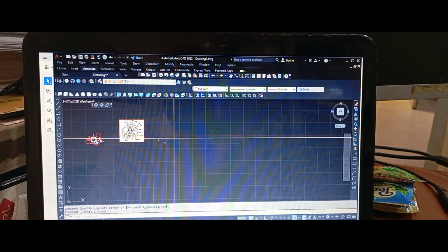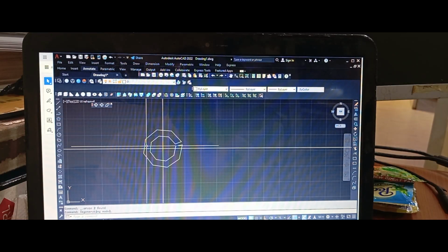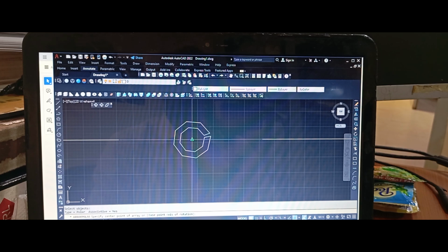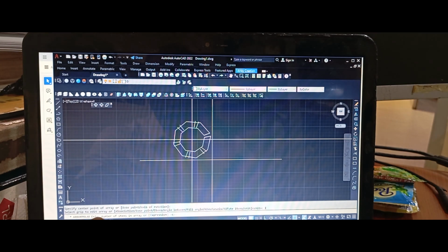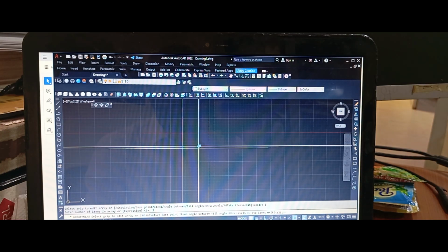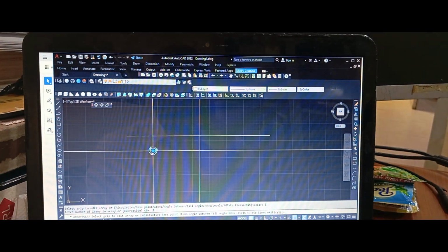What do I do? How many of them do I have? I have 3 of them. I can do the array of this. I'll array this. I'll go to cyclic array. You can hold down these cyclic paths and rectangulars. Cyclic. I'll select this shape. Next, I'll select the center of my array. I right click and say items. I say 3. With 3, you got all this redistributed in 3 pieces. That's what I have here. And that's what you're going to find here.